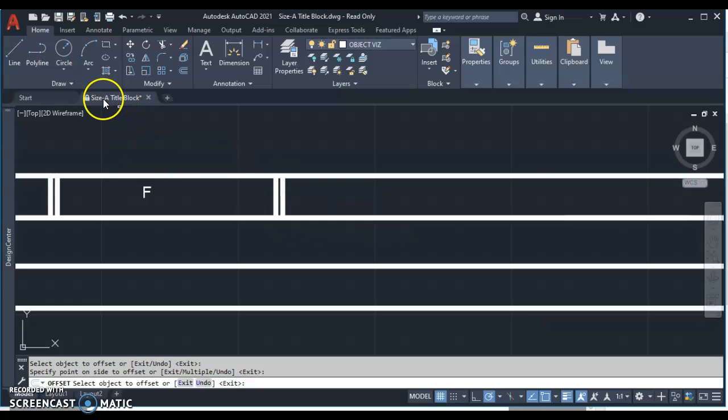And now we're going to set ourselves up for a 5 inch. So grab the line tool, mouse over the endpoint here. I'm not clicking, just extending in the direction I want to go, making sure I get the green extension line. I'm going to type in 5 and enter. So 5 inches from that endpoint. Now my line is here ready to draw my next part.